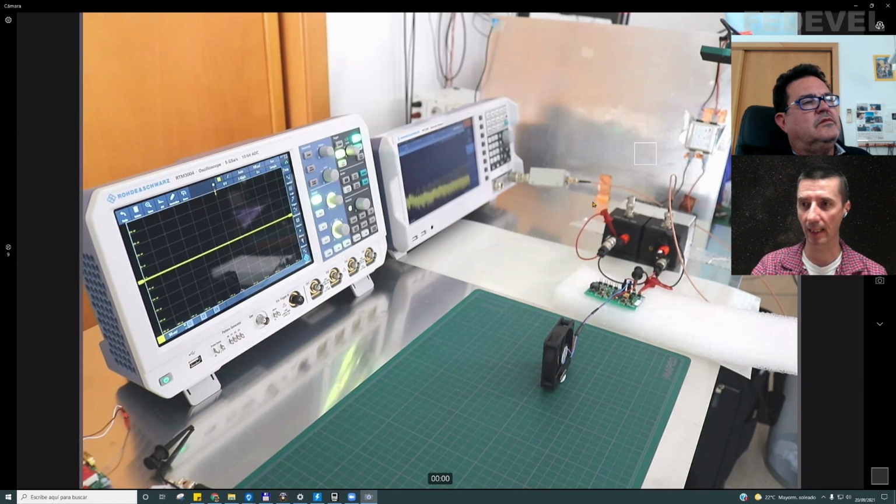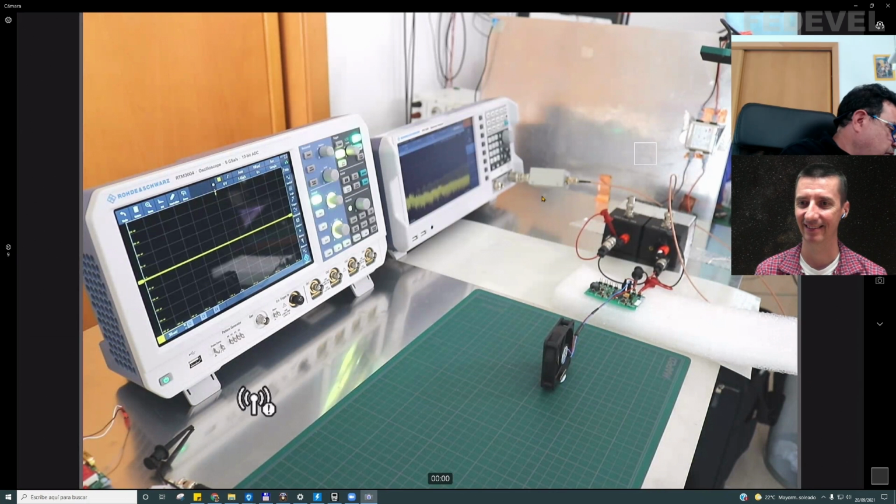So the spectrum analyzer is basically connected to the same ground as the ground of the big player. Exactly, to the earth system. Because this connector is connected to the chassis, which is connected to the earth, and this earth and this chassis are connected to the shielded connector of your coax cable. There is one more element that you can see. Yeah, this one. This is the transient protector.